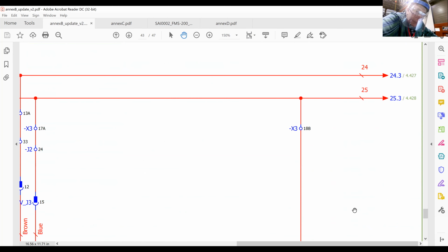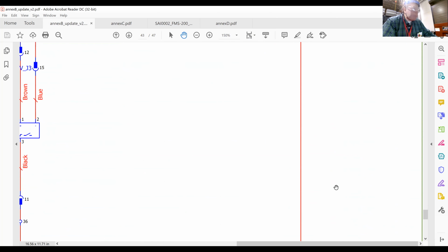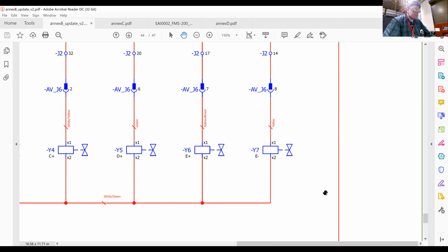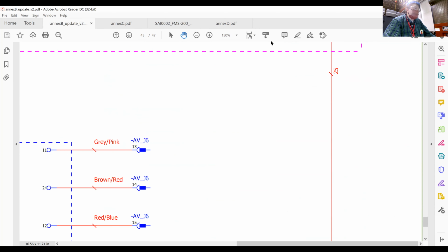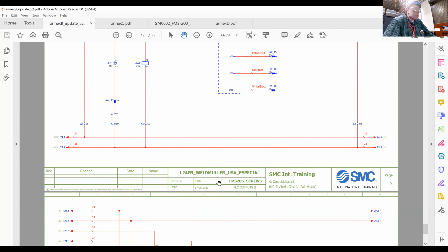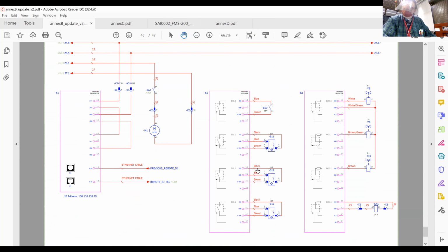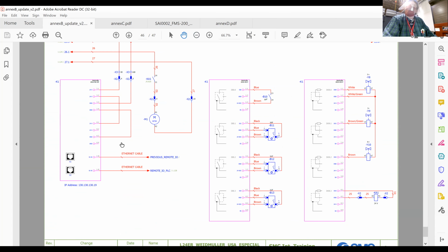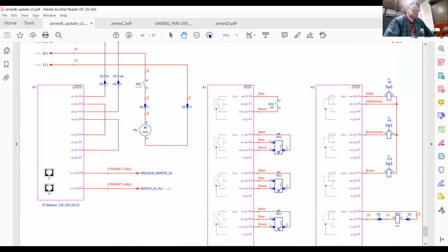It's going to be behind the machine, back in there where you see the remote I/O, up under here, where the Ethernet adapter card is. Everything that's out near the conveyor is run off of remote I/O. Now, if you look, this is on your page here, toward the end. And what do you see? Over in here, you have the Ethernet adapter module that has the Ethernet jacks on it. It's in the little chassis with the input module and the output module. All that stuff is behind. You can see it up under here where I'm waving, where the lights are blinking. You see that little module set with the lights up under there? Look at the output module. The output module is going to show us the Ka2 relay. So I'm going to enlarge and let you see. We're going to zoom in.